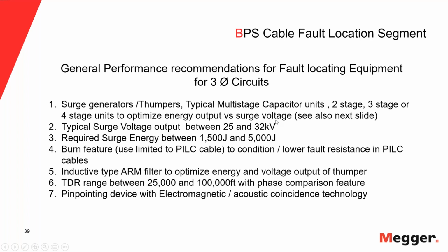So if I know it's in the paper section, then I can also much more freely use a burn feature, because a burn will only occur at the fault location. Some people are concerned. They say, "Oh, so much current." Well, let's put this all in perspective. A good burner has maybe 500 milliamps, maybe 1 amp. We make some burners that can do up to 20 amps.